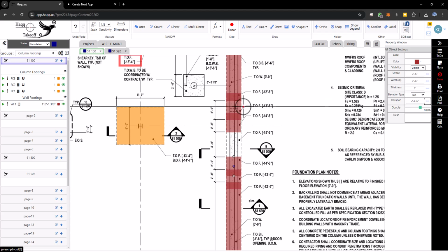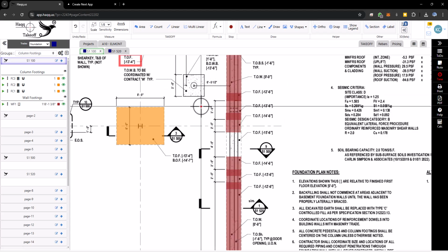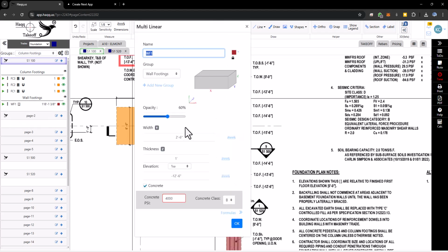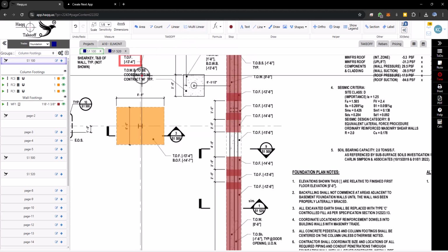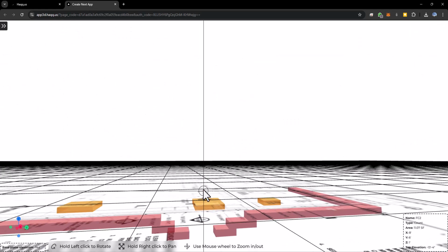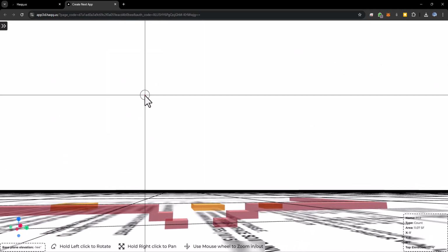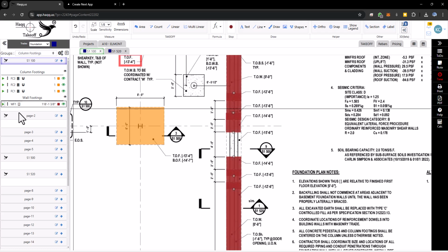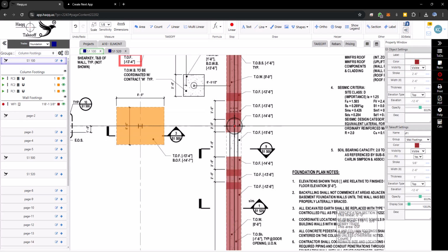Important note: if you go to the left panel, open the takeoff form under the Edit menu, and click OK, all WF1 elements will revert to their original elevation of -12 feet 6 inches, as these settings apply to all elements under the WF1 label. We're adjusting the individual elevations, but any global change in WF1 will reset them. To avoid this, you could create separate footing elements for each step, which would preserve individual elevations. However, for now, we'll continue using the same WF1 element.